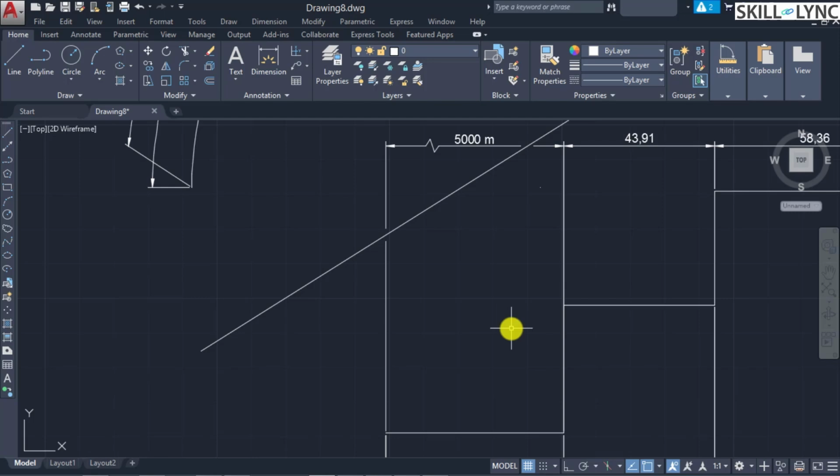So instead of adding a separate note, the frequency of inspection can also be included in the dimension line itself. These are related to tolerancing. We'll look into that next, but right now let us use the inspection dimension command to specify how frequently the given dimension has to be measured. That is invoked by the command dimension inspect.